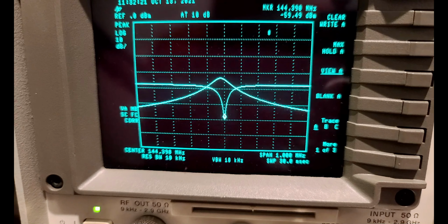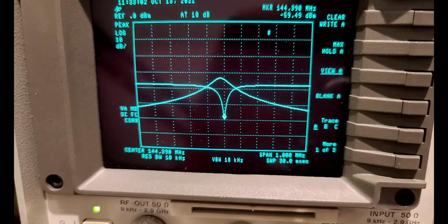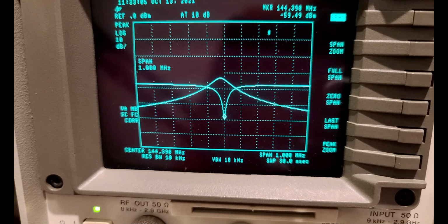So actually I forgot to tighten the lock nut on the fine adjuster. Anyway, you can appreciate, if you were to compare and contrast the transmission loss before and the return loss after tuning, the value of having that capability of a transmission loss method and a return loss method, and also to be able to reference both of those graphs through this feature in this spectrum analyzer called Trace. I wonder if I can go back to my span and go to, let's say, 25 megahertz. Okay, that doesn't make any difference because this is a snapshot.